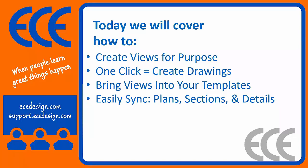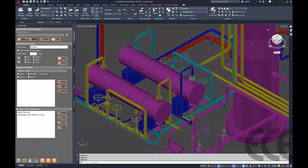to take those same views and bring them into your template so you have a little bit more control over different design styles and different drawing styles as you're walking through that process. And finally, we quickly sync your plan sections and details. So instead of using the Ortho, which can take quite a while to reset every single time a change happens in your model, we're simply using XREF in this process. So if anything changes in the model, all you have to do is reload that XREF and go right into it. So let's take a look at Plant 3D and get a few work cases set up here.